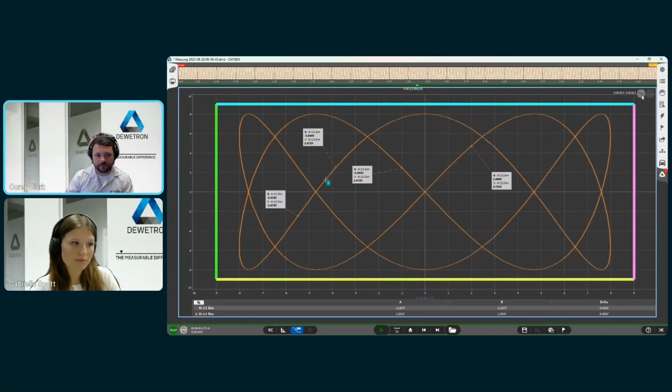Additionally, we also have the cursors. In here, we click the cursor button. It brings up our cursor box at the bottom, and we can just highlight a part of our curve to place that cursor and then place the second cursor. That will give us a delta value between A and B right within the cursor box itself. And just remember what I mentioned earlier: these data labels are persistent to the instrument itself. Once the instrument goes away, the data labels all go away. So be sure to save this instrument and don't delete it by accident before you use it for reporting. And that would be the new XY plot improvements in Oxygen 6.